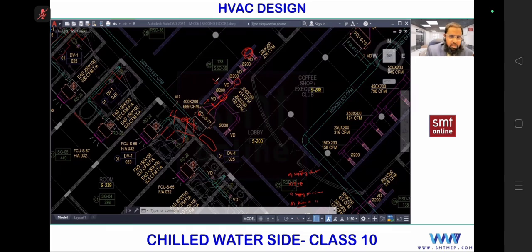Do you understand? Yes. Now case 2 you can write. Case 2 you can write AHU with... Is this return air terminal that you mention hypothetical, or will it actually be there? It will actually be there, na, because when the suction takes place through this return only, so if there is a return, that pressure drop you need to consider, take into account in the fan selection. This is for what? Case 1. So only with supply duct. Case 2 you can write AHU with supply plus return duct.